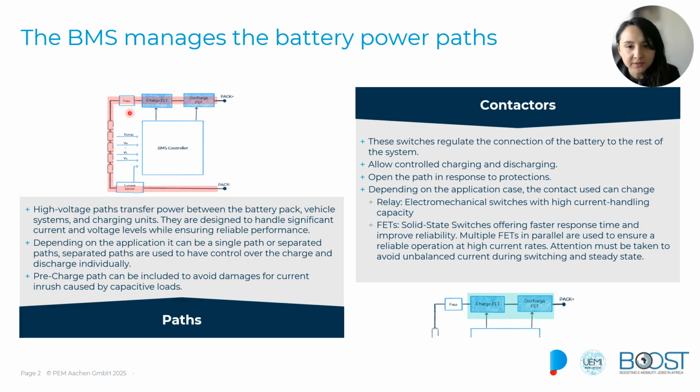We also have fuses that will protect the systems by disconnecting the power path during overcurrent events. And we also have the contactors, that are one of the most critical components in the power path. These contactors are like high current switches that manage the connection and the disconnection of the battery pack.